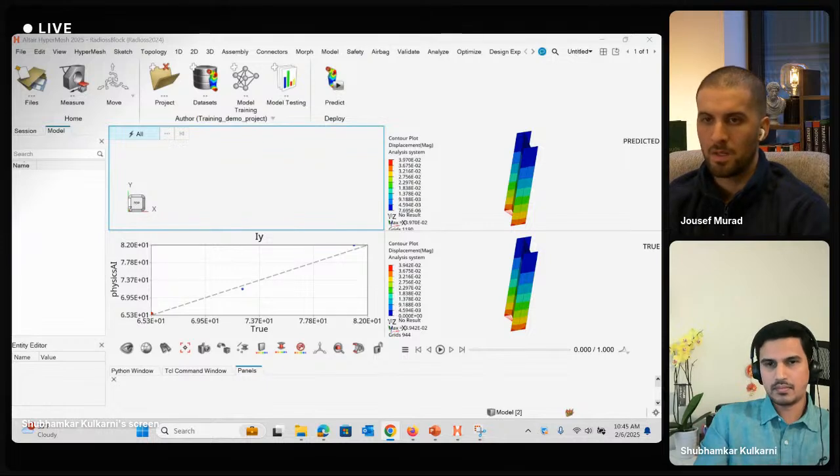That's great. Okay. Last question from my side. How do you handle the trade-off between accuracy and the computational efficiency when you apply this geometric deep learning to more complex simulations? Yeah. So clearly, there are certain good practices that should be followed. For example, you can't expect a physics AI model to create something out of nothing and to predict everything. So if you have like 10 responses across eight load cases, that's not a good objective to ask physics AI to predict everything in one go. So you have to keep it focused.